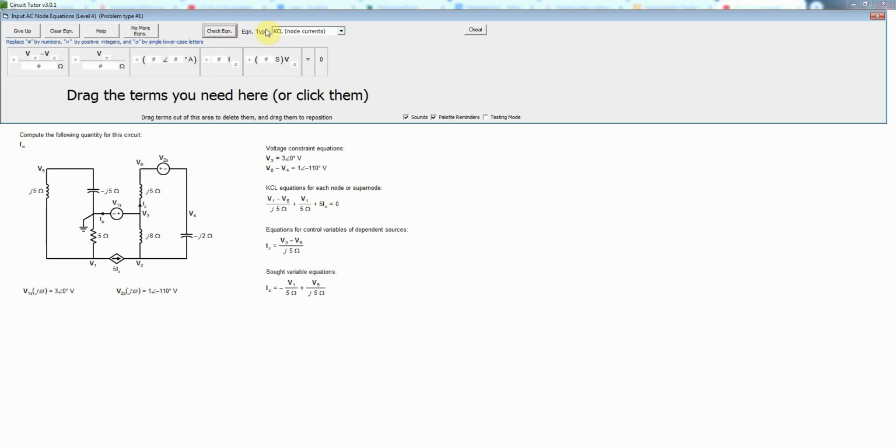And that is correct. And now we'll write a KCL equation for node 2. So now we have this term entering, so we'll have one of those, and then we have two impedances that are connected between nodes, so we'll have two terms like this, and that's all going to be equal to 0 by KCL. So let's add the current going this way. Now that's the negative of 5ix.